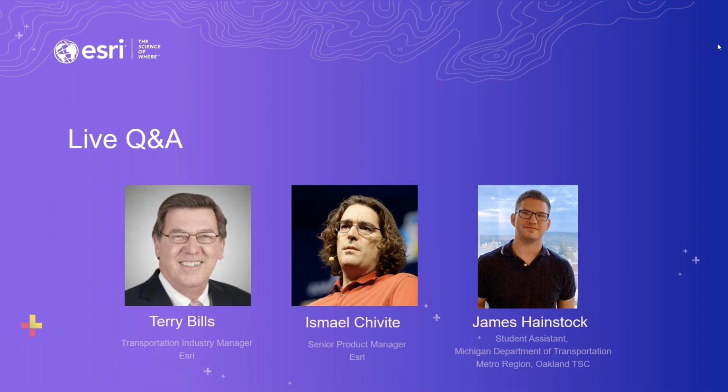There was a question: can QuickCapture support UTM coordinates? And is it possible to configure through ArcGIS Pro? Sure. On the first one, UTM coordinates, you can definitely target a feature service that is using UTM spatial reference. The application itself always works on lat-long WGS84, but we can do on-the-fly projection to enter the data as UTM into your own feature service.